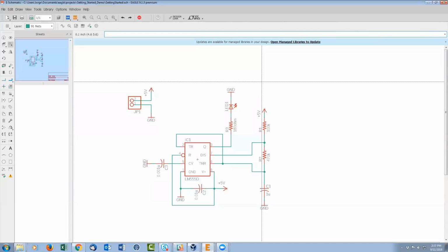Okay. I'm going to continue shooting questions at you because there are a lot coming in. Is there an option to have EAGLE place the components on your behalf at the best possible location for auto routing? Define best. That's the big problem. There's no universal definition of best. Over the years, there have been attempts at making auto placement ULPs, and there's several. Users made a whole bunch.